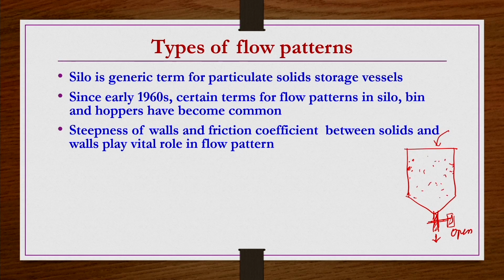So, that is the solids and the interaction, the friction between the solids and the container wall, whatever is there. That one is one of the important factors, along with the steepness of the walls. So, how steep are the walls? That is also going to have a role in what kind of pattern is going to be developed inside this storage vessel.